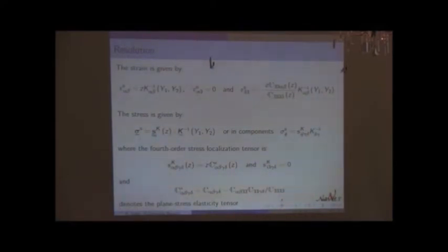It's a tensor mixing 3D and 2D, because you want to contract with the curvature. It's just the linear superposition, and you will end up with a 3D stress tensor inside the plate. Is this clear? Maybe it's not completely obvious. And with this definition, you retrieve the definition of the plane stress stiffness.